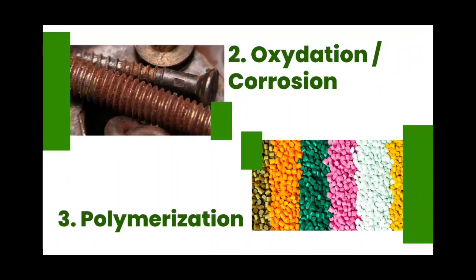Electrochemical corrosion of metals occurs when electrons from atoms at the surface of the metal are transferred to a suitable electron acceptor or depolarizer. Water must be present to serve as a medium for the transport of ions. The most common depolarizers are oxygen, acids, and the cations of less active metals.